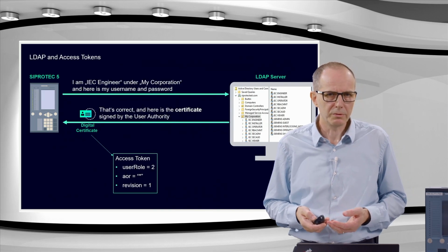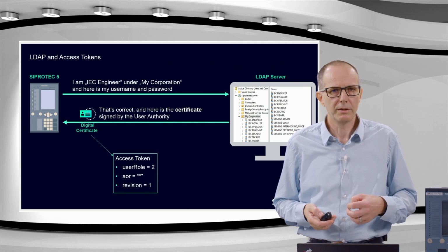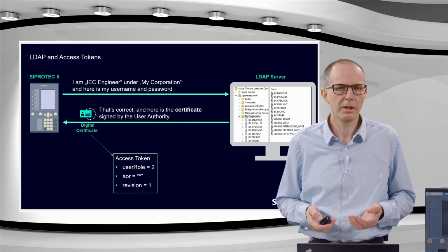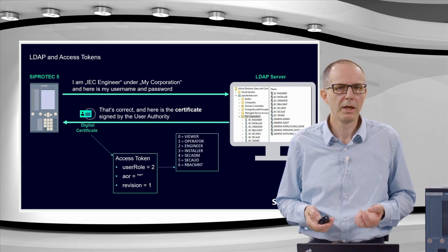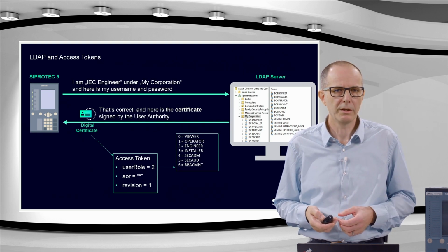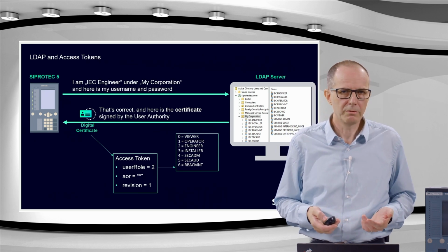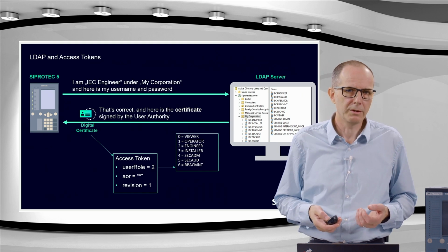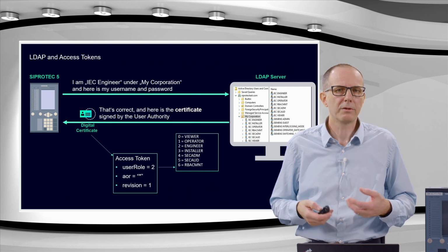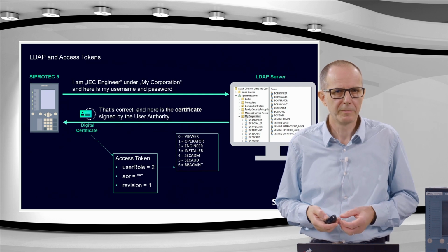According to the IEC 62351 extensions, the role details are stored in a list with a minimum of three mandatory criteria. The first criterion is the user role, of course, represented as an integer for a predefined user role in IEC 62351. For example, for the engineer role, the value 2 is defined. Besides these roles, definition of extra roles is possible with a range of -1 to -32,000.